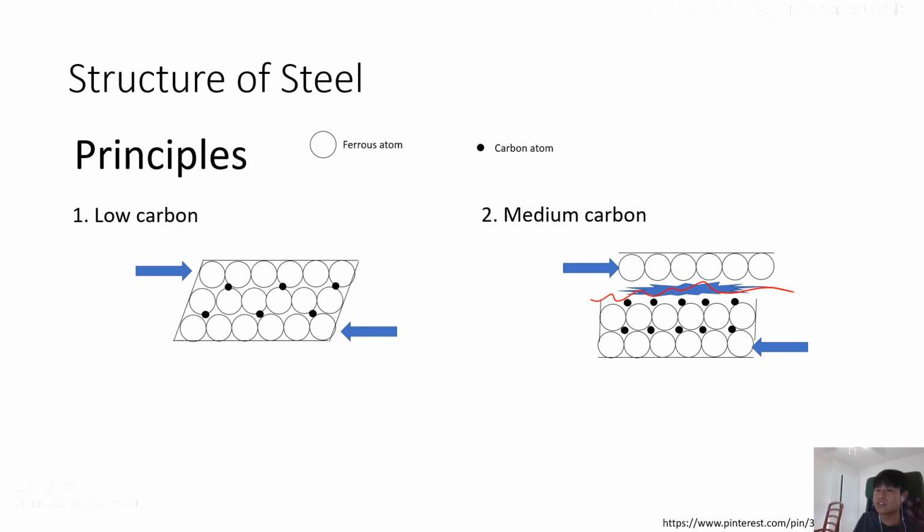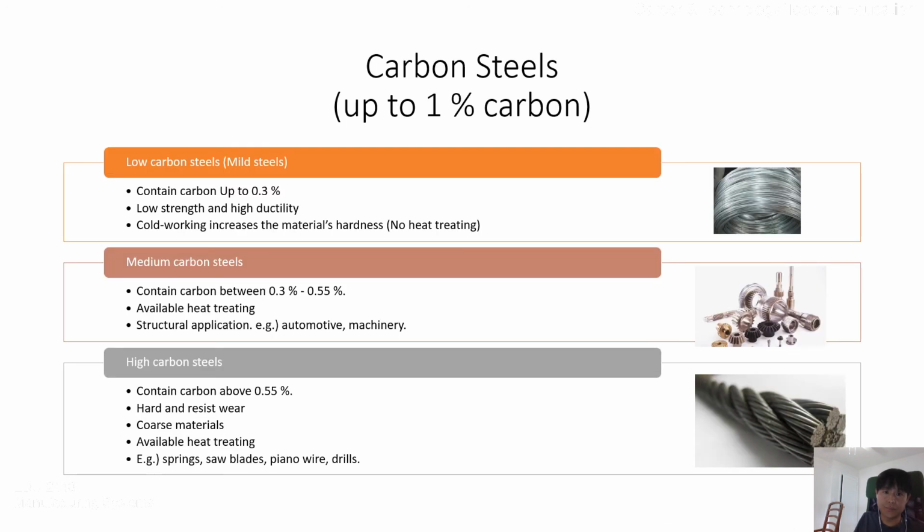Cast iron is very sturdy, very rigid because of the carbon that holds the structure against the outer stress. But after getting stress above a certain level, it breaks. But low carbon usually does not break. That's the difference, right? So let's apply those concepts to actual products.